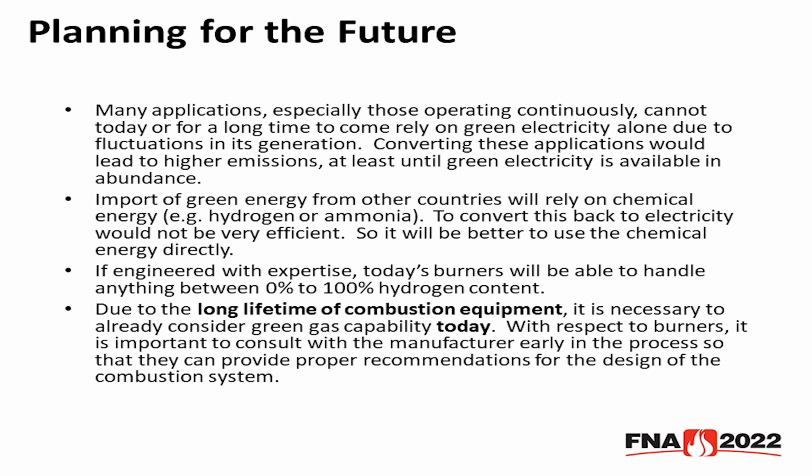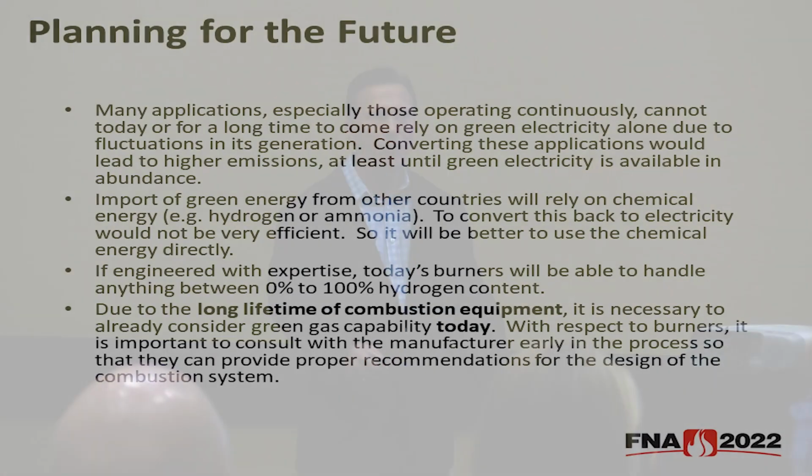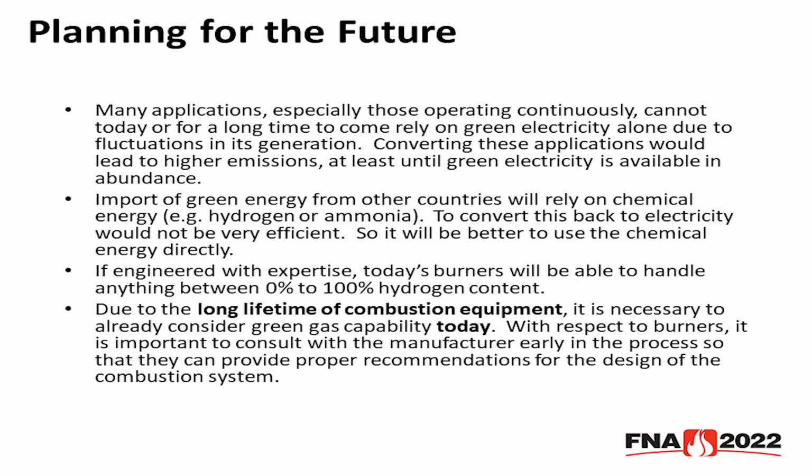If designed and engineered properly, today's burners will be able to handle anything from 0 to 100% hydrogen. Okay, and due to the long lifetime of combustion equipment, we're talking like 20, 30-year investment typically, it's necessary to already think about green gas today. So you need to talk to your manufacturer early in the process so they can provide recommendations, because you don't want to install a system today and then have to replace it in 5 or 10 years because now you need to operate on hydrogen. Not all systems are going to be capable of that.